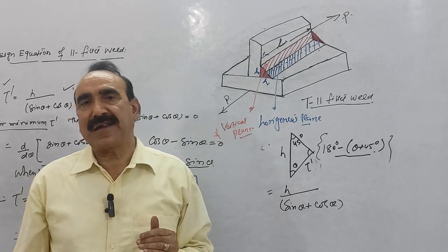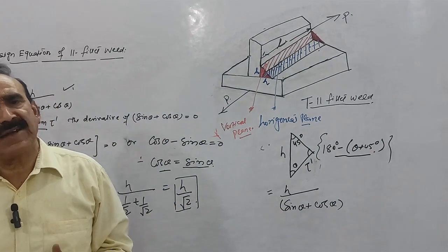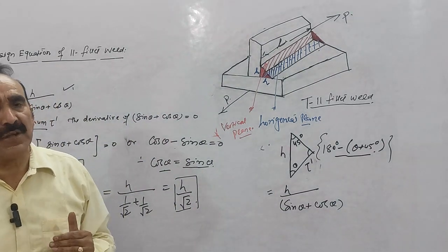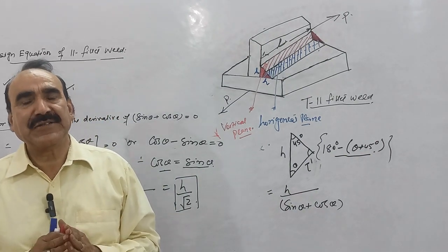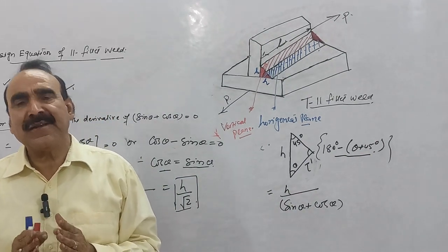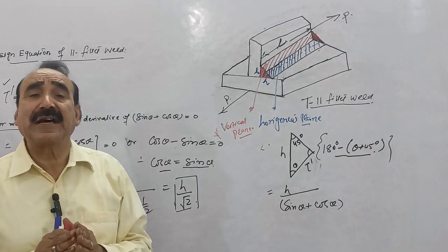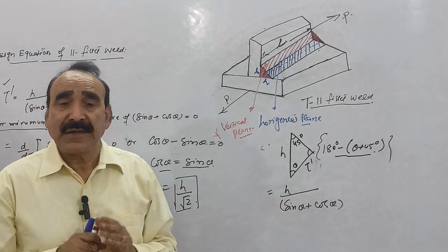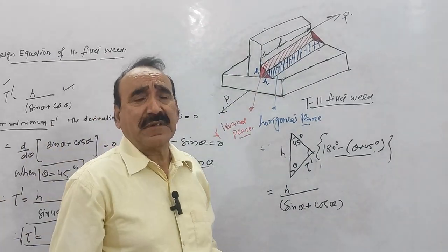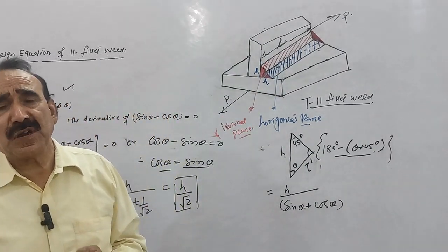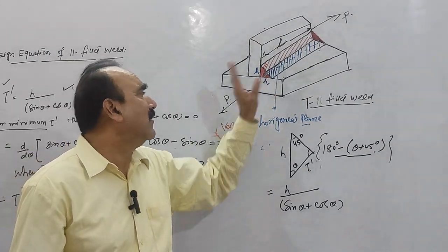When the force is parallel to the different planes, which stress will be produced? You will get the shear stress. Now the question is, if I take the horizontal plane, then the cross sectional area of the belt will be equal to H into L.